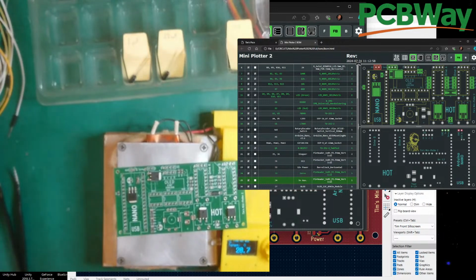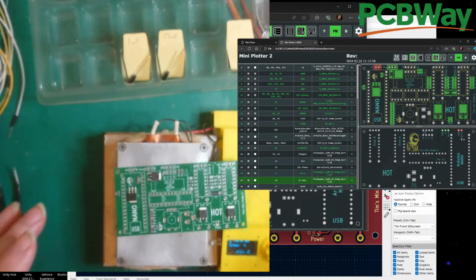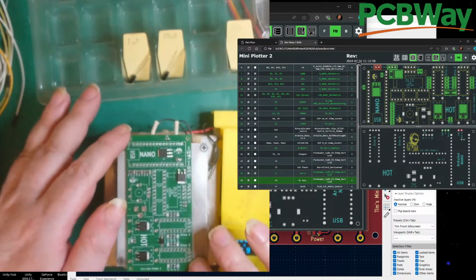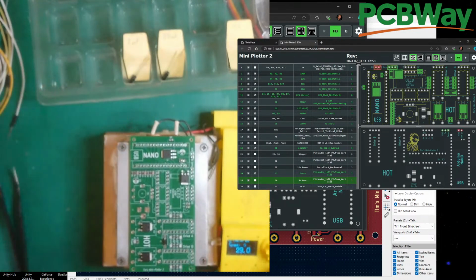I've tried to explain why these overshoot, because they're a PTC heating element, and we've got a big lump of aluminium which we've got to heat up, and then once it gets to a certain temperature it takes forever to cool down. So you're better off bringing it up to a level just below what you want and then bring it up slowly after that. In fact, you should do that with any heater, hot plate or whatever you want. You should always bring it up to a preheat, then take it up to the final heat. So let's move that around that way so we get more on, and let's bring it up to 180.